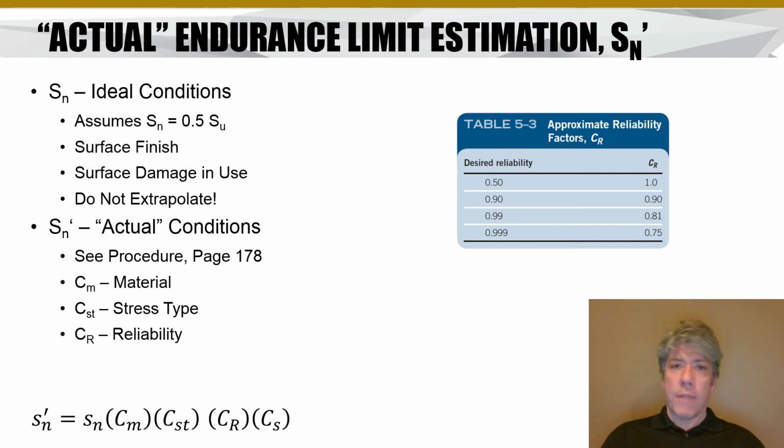The reliability factor is next, and if you think about the way that the SN curves are usually made, well, experiments are performed and then that data is just best fit. Well, that means that the line is at the 50% failure, right? Consider one particular SN pair from that line. If you ran 10 experiments there, you would expect half of them to fail at that number of cycles and half of them to not.